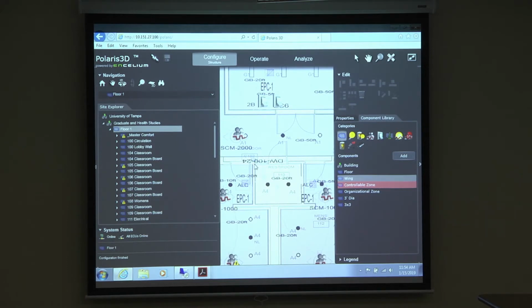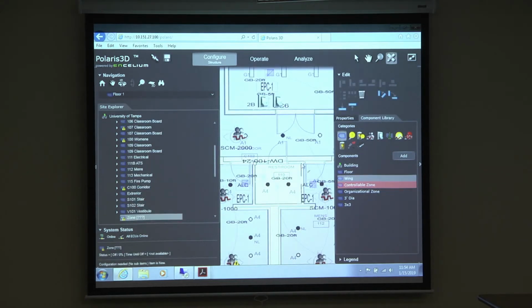So I go into a corner right here, click, click, click, click, right? I'm just trying to get the building outline, which is the zone. And I double click, and then that's done. So right now my mouse still has that thing on the end of it, so if I keep clicking, I'm going to create more zones. So I've got to go back over to the pointer, right?